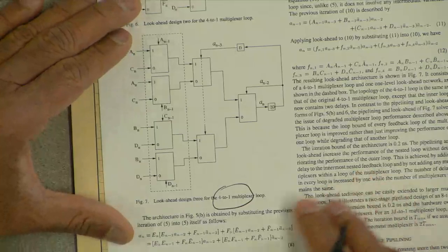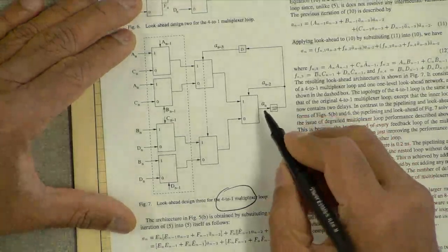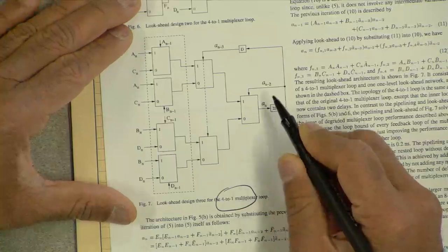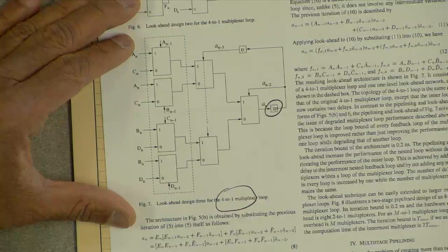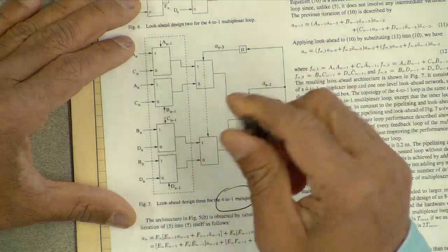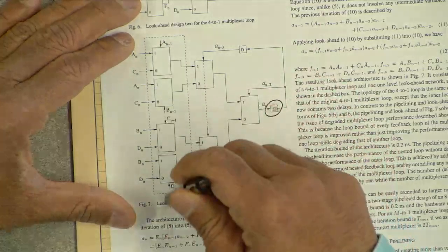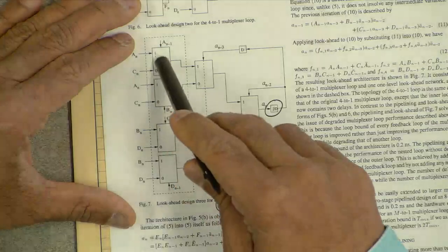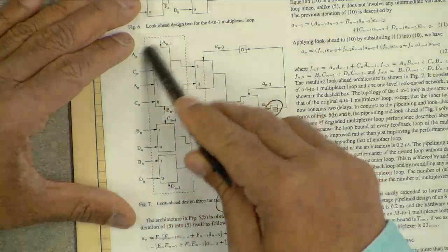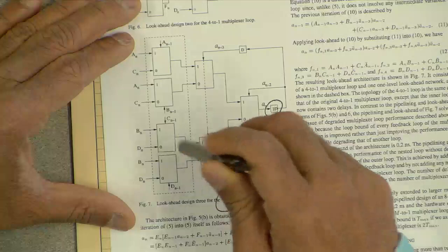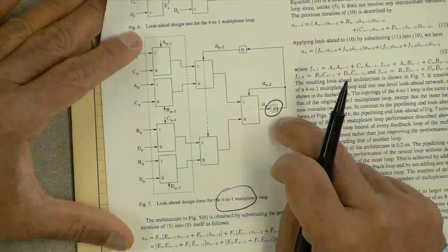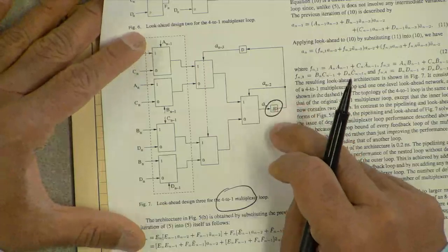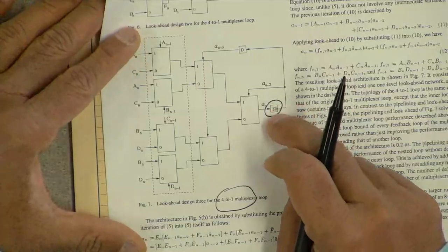And then the inner loop, now we have used look ahead to increase that number of delays from 1 to 2, and that says that we can have these extra 4 2 to 1 multiplexers outside the feedback loop that we can pre-compute. And there is still more work to be done because these 2 delays are sitting here doing nothing.